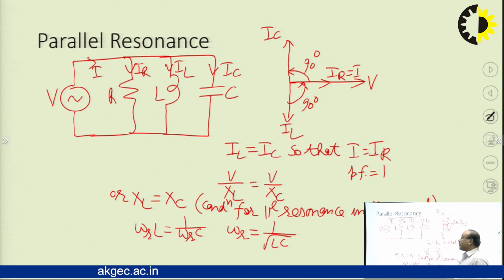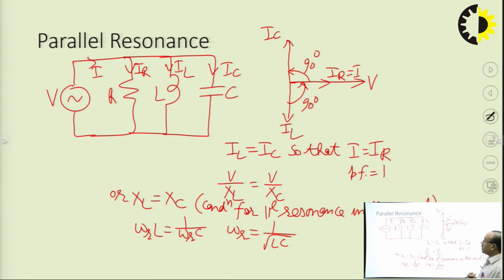So depending upon the circuit connections or circuit configuration, we can find the condition for parallel resonance, and then the resonance frequency and impedance of the circuit, which is known as dynamic impedance in parallel resonance. Here, dynamic impedance ZR, which is the impedance at parallel resonance, will be equal to R only, since supply current is in phase with voltage and is equal to IR.